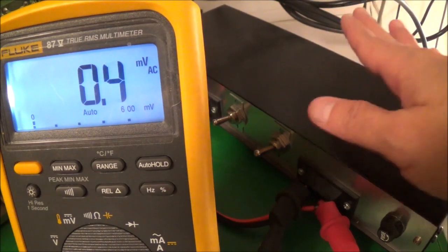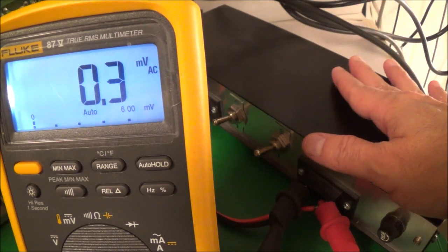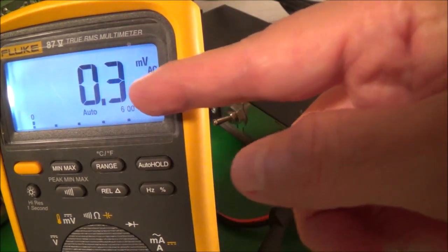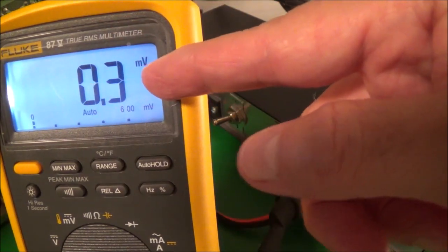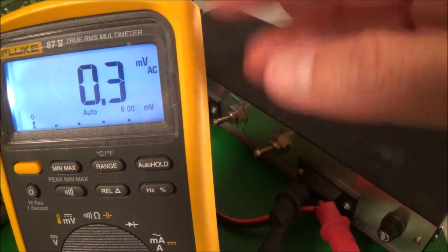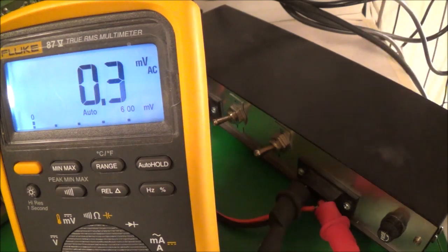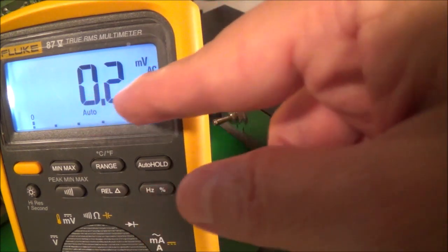Basically what I want to have, this is the way I like to do it, is 1 watt output into 8 ohms, and then I would read on the meter about 2.82 or 2.83 volts. It doesn't really have to be that exact, but that's giving you a 1 watt output. What I do for that is I turn the volume control all the way up and the function generator control all the way down, and then I slowly bring up the function generator until I reach 2.83 volts.